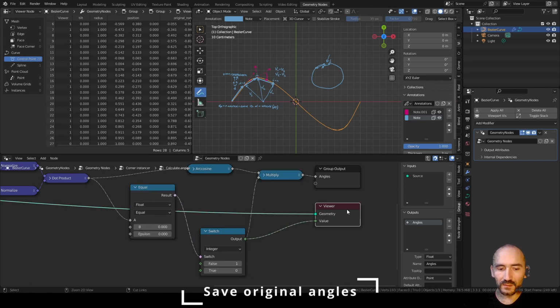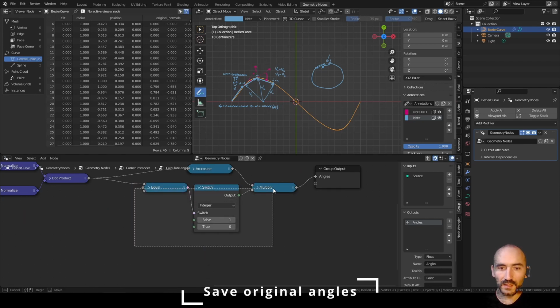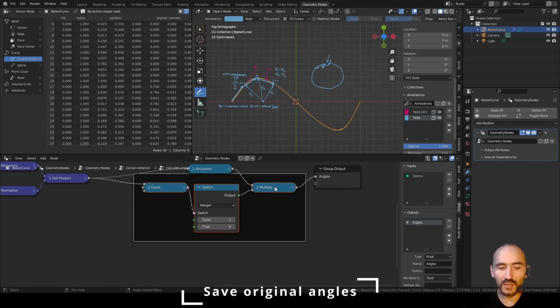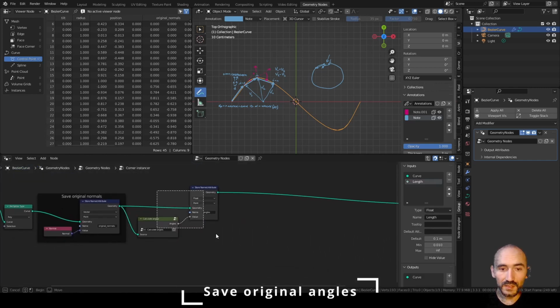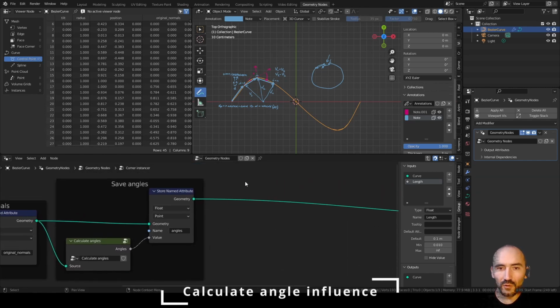Now I can cut these, I can select this node, Ctrl J, F2, avoid bad values on start, and now press Tab to exit from this node, select these two nodes, Ctrl J, F2, save angles. Now you can see that for all these vectors I have always a positive number.